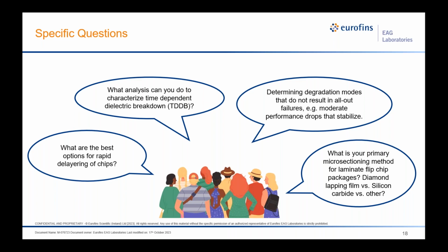Sure. So this is a very specific kind of technique. It's generally requested by fabs. To give you some background, when they process transistors or MIM or MOM caps within a wafer, they'll also make other structures in their test areas, like the test structures on the wafer scribe lines. In those scribe lines, they'll make the caps at the same time as they make all the gate oxide and all the MIM and MOM caps. And therefore, we'll do the testing on the scribe line structures, and that'll give them some confidence in the actual construction of the wafer and the quadrants, or however they dissect up the wafer.